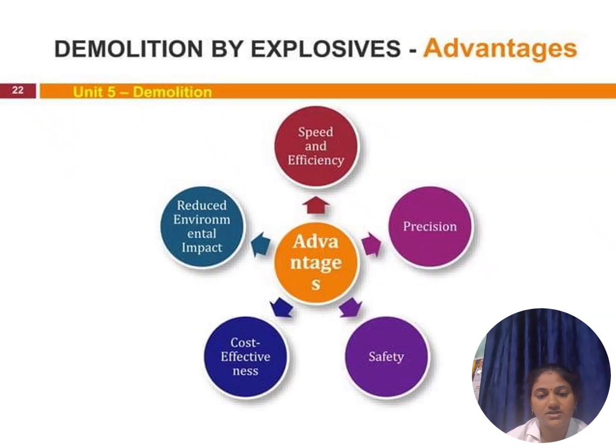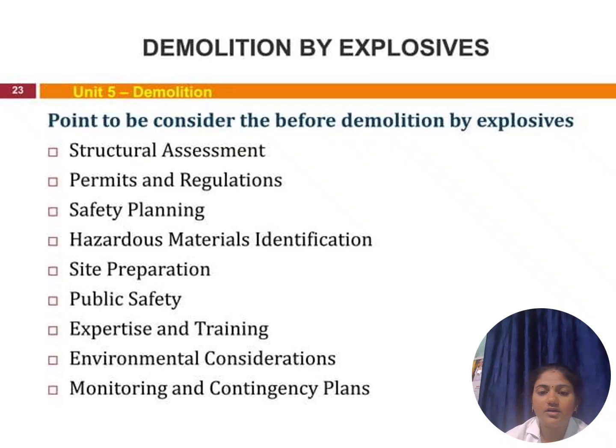And then by using demolition by explosives, the advantages are safety, cost effectiveness, and reduced environmental impact. And while coming back to the next one, it is precision. And points to be considered before the demolition by explosives: the first one is structural assessment, whether it is in need of explosives or not is considered, and then safety planning and hazardous material identification, as that may lead to the complete collapse in a dangerous manner. So they are considering it. And then site preparation, public safety, expertise and training, and environmental considerations.